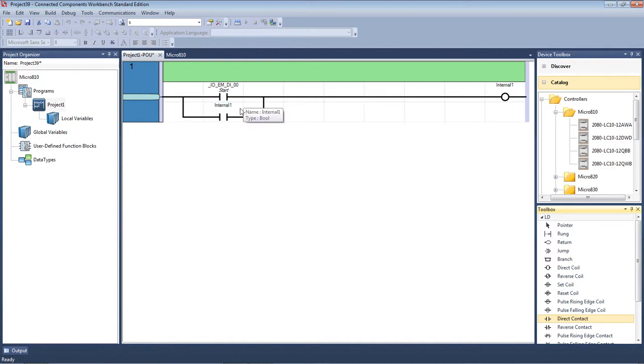Now the logic here is very similar in terms of our circuit diagrams. So we have all the action elements in this part of the circuit. For the outputs, we only have the one output for any rung. So we can't put outputs in series with each other, as you would do with a circuit diagram. You can picture these as the coils of a relay, so they don't go in series. So if you need extra logic, you can build a new line below and put a new internal relay in.